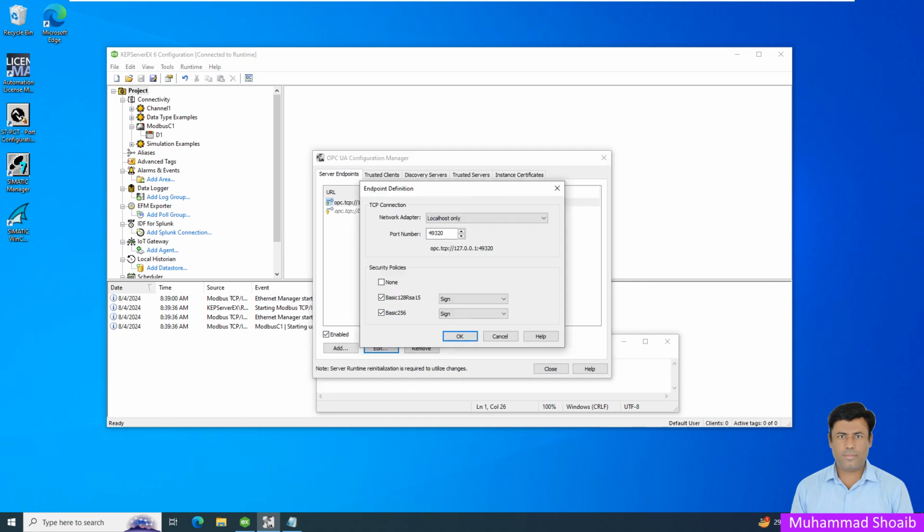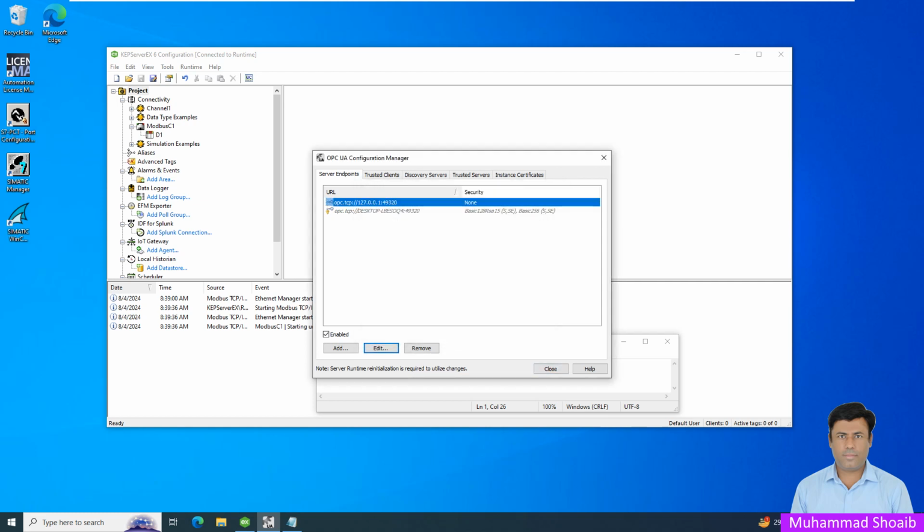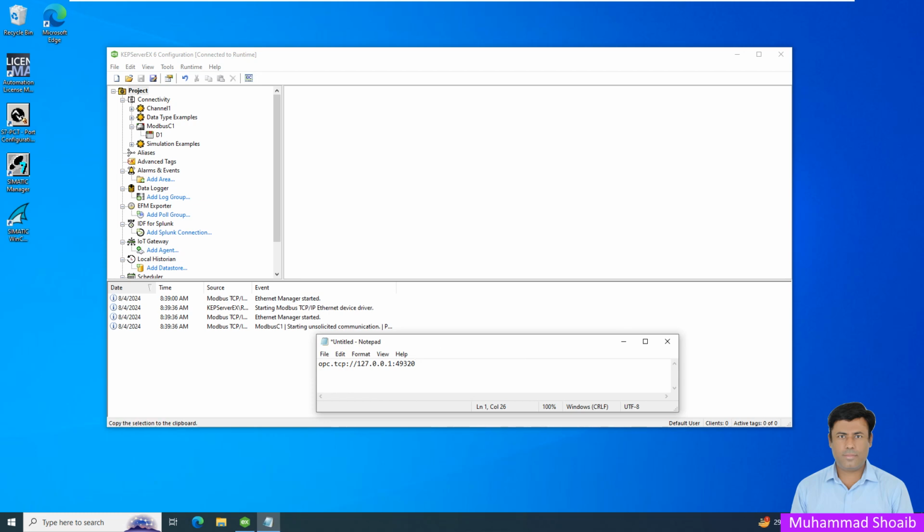In this tutorial video, we are not going to use any security policy. Later in another tutorial video, we'll use the security policy and see how WinCC and the KEPWare server share the certification with each other. But in this tutorial video, we're not going to use any security policy. So I will untick this security policy and select the none option. That's it. Click OK, and then click close.